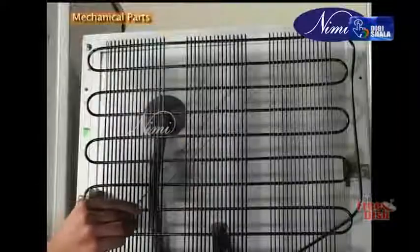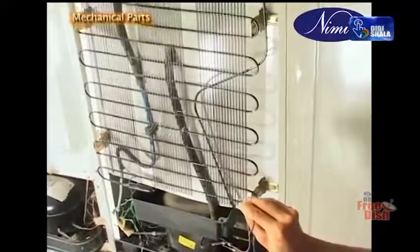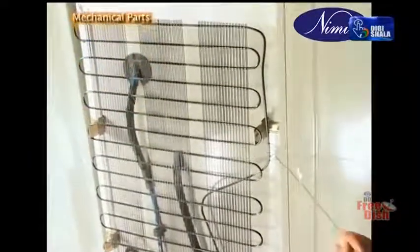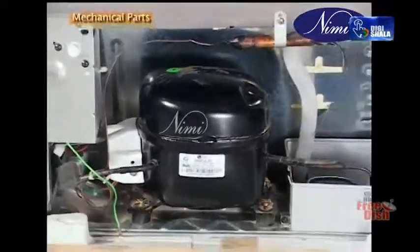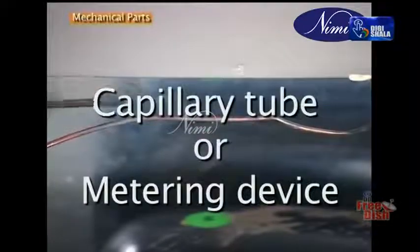Condenser. Condenser works as a door to discard the heat absorbed by the refrigerant at the evaporator, plus the heat added at the time of compression, and the refrigerant gets liquefied. Filters, dryers. To sort out any foreign particles and moisture, not allowed to enter into the orifice of the metering device. Capillary tube or metering device.